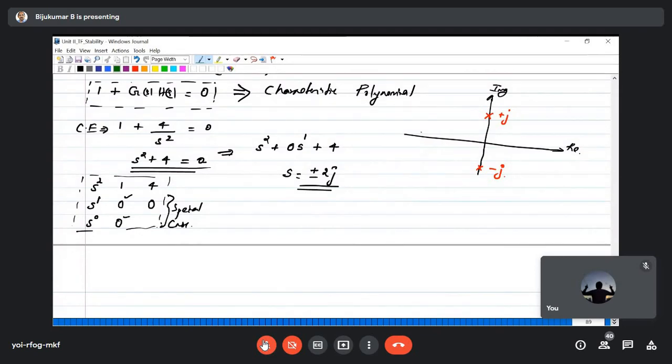It won't be critically damped, right? Because obviously some sinusoidal term will be there. Critical means there won't be any oscillation, right? Sorry, not underdamped, undamped. Because what is zeta in this case? Zeta is 0, right? So it's an undamped system.